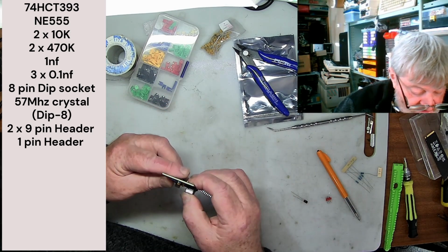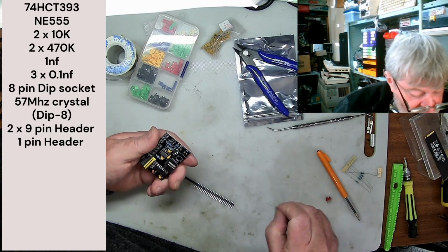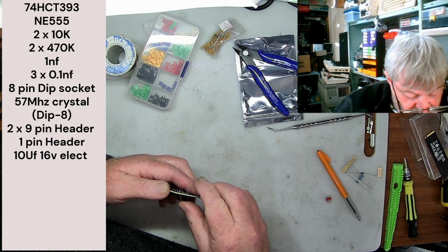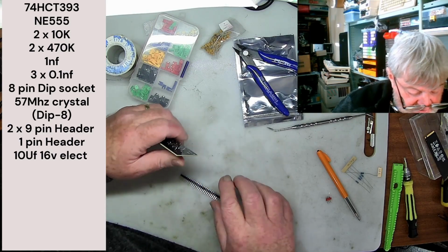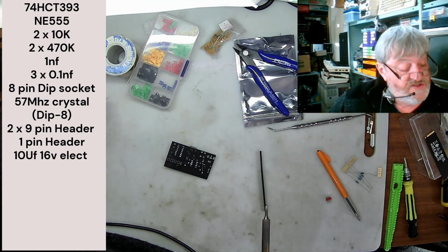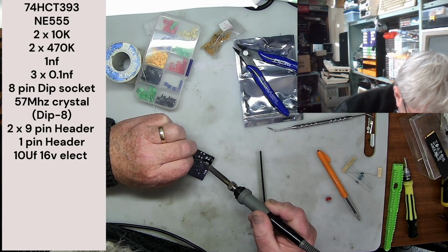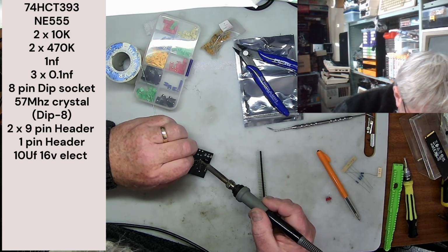But I'm not going to use the ground anyway. The reset is just for resetting a CPU, and I don't know if I'm going to need it, but if there's an issue with the 728 with the circuit, then it would be handy to tag it into the reset line. So the whole thing has a purpose then.